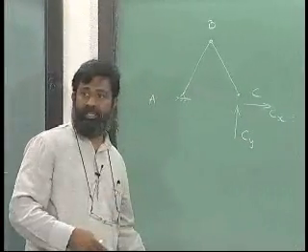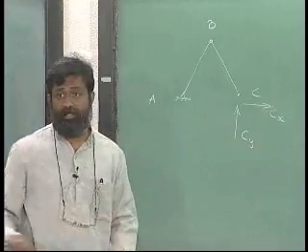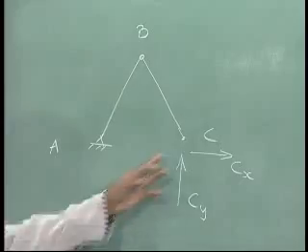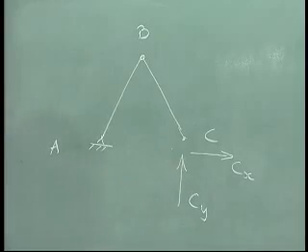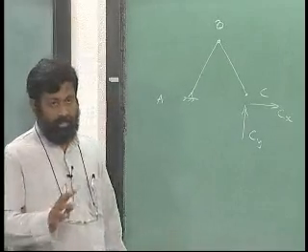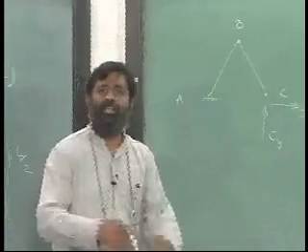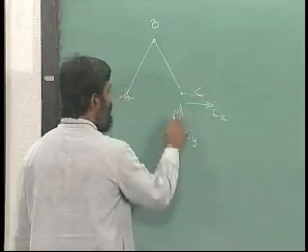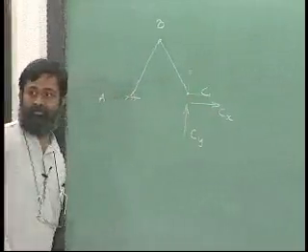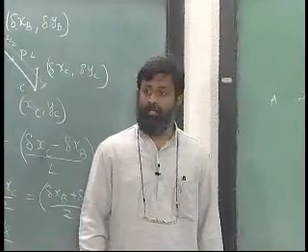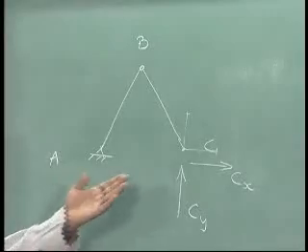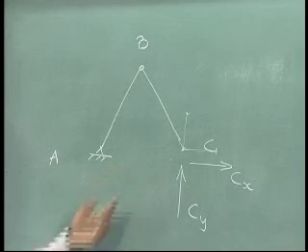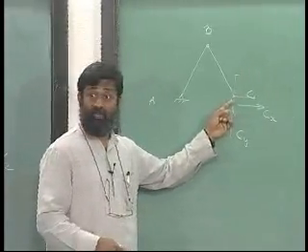If I need to find out both the reactions, what can I do? In the earlier exercises that we have carried out, we only said you release one of them. In this particular case, I have released two of them. What shall I do? The answer is not very difficult. Apply two virtual displacements, one along this direction and another along this direction. The question is, can I? The answer is yes, because the number of degrees of freedom for this system is 2. I have released two of them here.